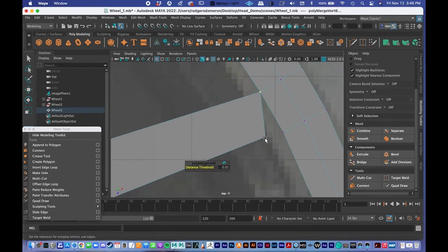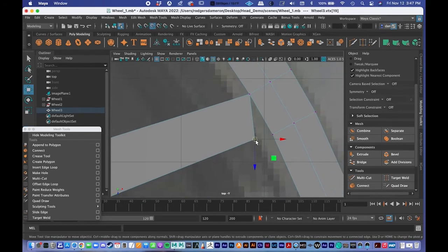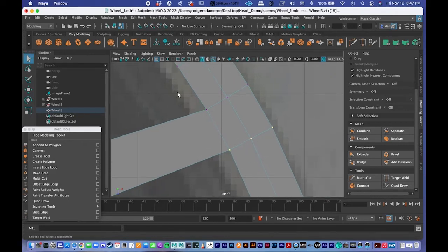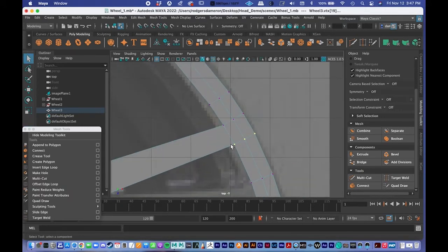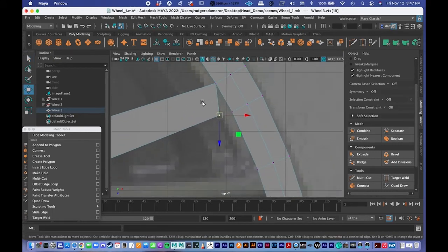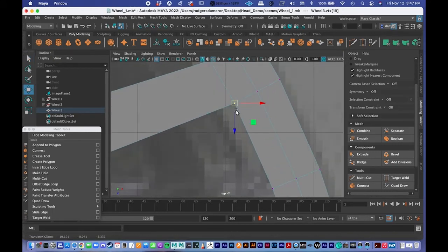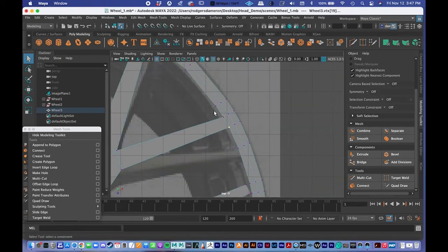One thing that's really important here that I need to mention is that I snap those together. If I drag and select a bunch of vertices like that, or if I drag and select vertices like that and then press merge, it looks like it goes okay, but just don't do that. It can really cause some problems for you. So I'm just going to edit undo to make sure that that doesn't happen. When you merge vertices together, just make sure that you're merging the vertices that you want to have welded together, right? Like I don't want to weld these vertices together with those vertices, you know? So just drag and select here and then press merge.